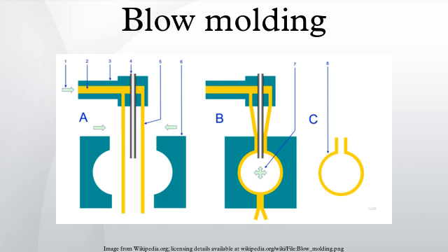Extrusion blow molding. In extrusion blow molding, plastic is melted and extruded into a hollow tube. This parison is then captured by closing it into a cooled metal mold. Air is then blown into the parison, inflating it into the shape of the hollow bottle, container, or part. After the plastic has cooled sufficiently, the mold is opened and the part is ejected.